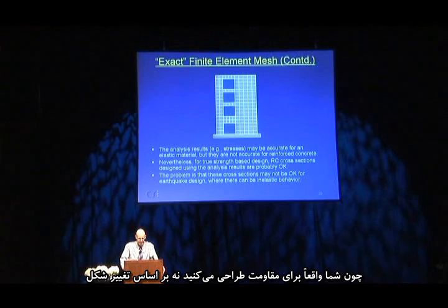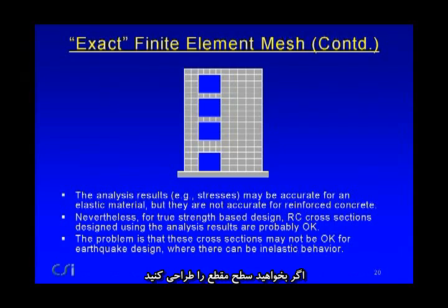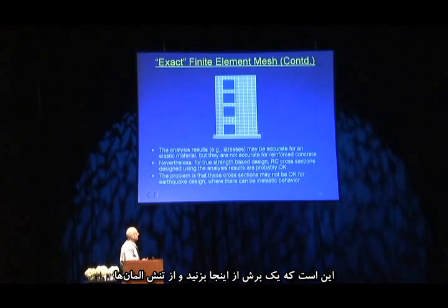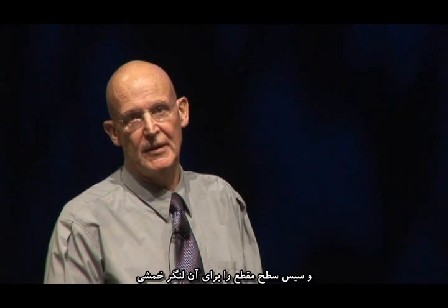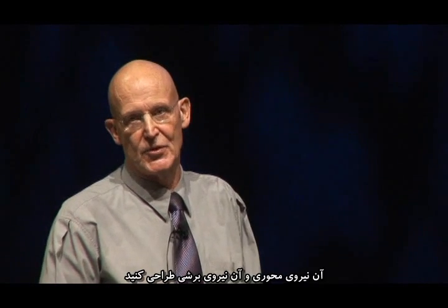That's not your concern. Your concern is not to get an accurate analysis. Your concern is to get some forces to design the cross-sections. And the sort of thing you might do, and I want to talk to you here about true strength-based design, where you really are designing for strength, not deformation-based design. The sort of thing you might do, if you want to design this cross-section, is take a cut through here, and from the stresses on those elements, calculate the bending moment and the axial force and the shear force, and then design that cross-section for that bending moment, that axial force, and that shear force.